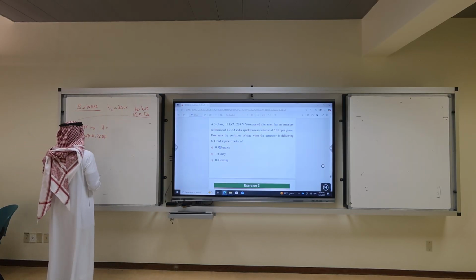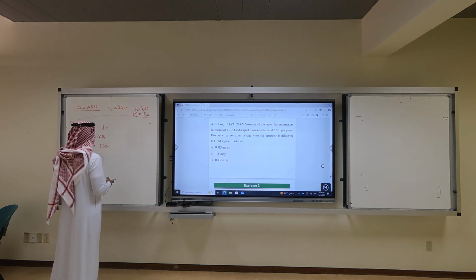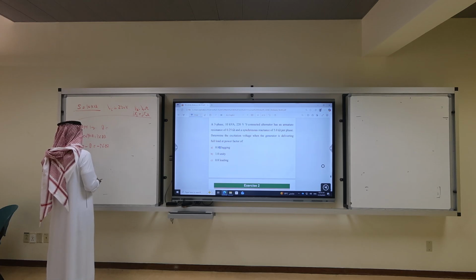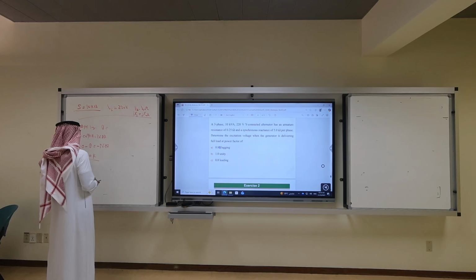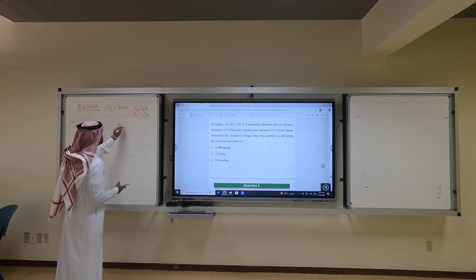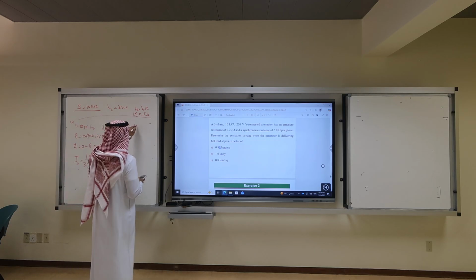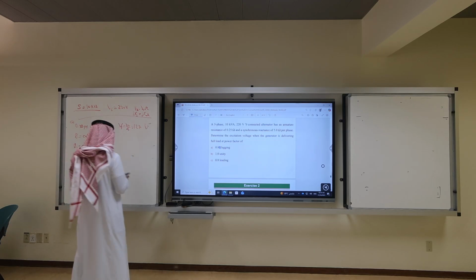So what is theta I? Minus 36.87. So what is IA? 10k over 3 times 220 over square root of 3, because V terminal is 220 over square root of 3. 127 volts.